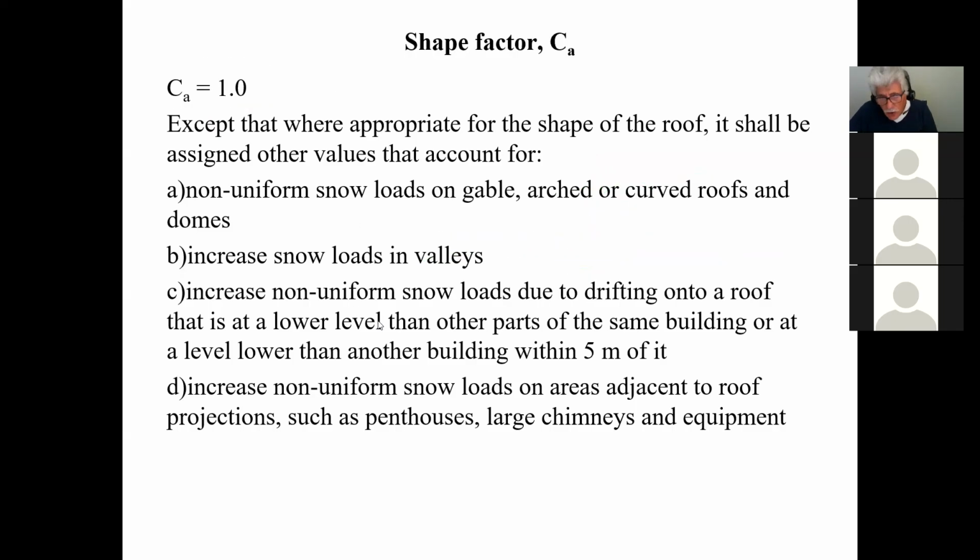And if you have large equipment, like large air conditioning equipment, all around those things you have to allow for an additional snow load. So that's what the shape factor is. The shape is no longer just a straight level of snow; the shape allows for a different accumulation, therefore the load will be heavier. And that's what we're going to try to do.